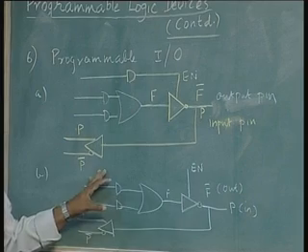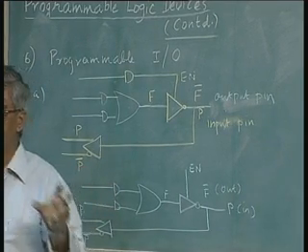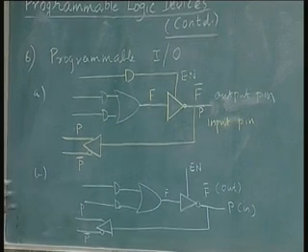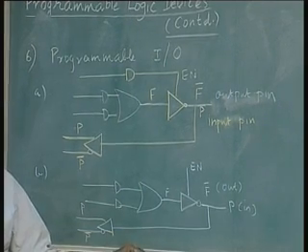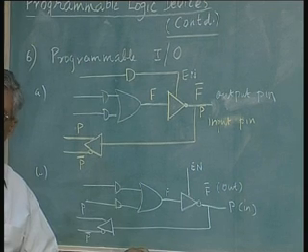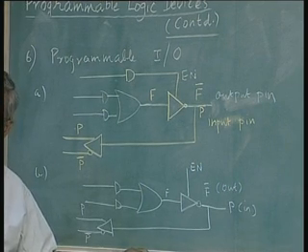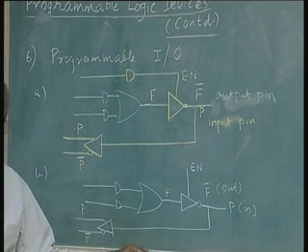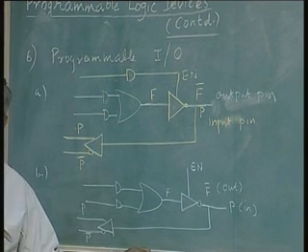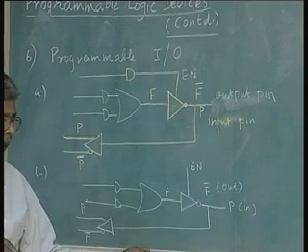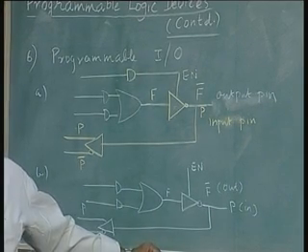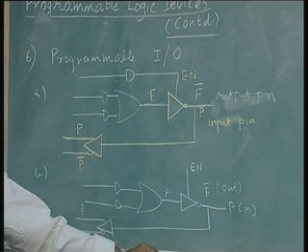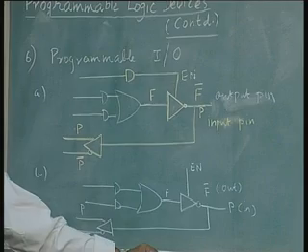This is a feature which is very popular, because for a given device size, you may want to design a system with more inputs and fewer outputs, or more outputs and fewer inputs. To match a wide variation of inputs and outputs using a given device, we use this option. If this option were not available, what you would have done is to go for a bigger device which can accommodate more inputs. Supposing I have 10 inputs, and I have a device with only 8 inputs available, I will have to go for a bigger device, and a 10 input device may not be available.